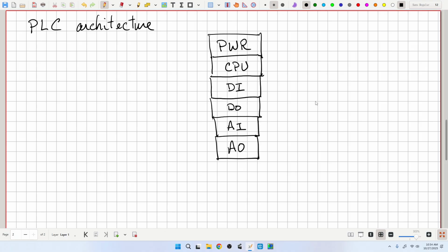Now, different manufacturers may have different conventions, but generally, for your digital inputs, you'll have designations such as maybe %IX 0.1 for one of those input variables, and you can then associate that with a text variable name in the program. So the IX indicates a digital input.